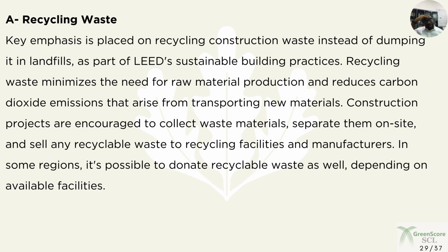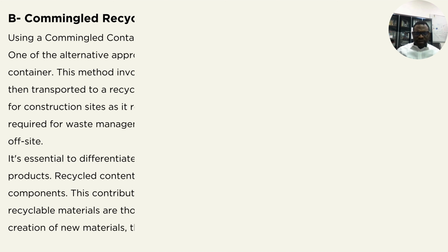Reduces carbon dioxide emission that arises from transporting new materials. Construction projects are encouraged to collect waste materials, separate them on site, and sell any recyclable waste to recycling facilities and manufacturers. In some regions, it is possible to donate recyclable waste as well, depending on the available facilities.